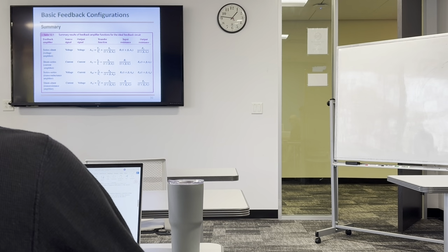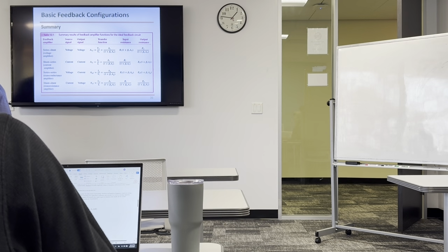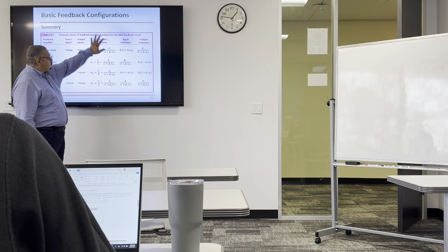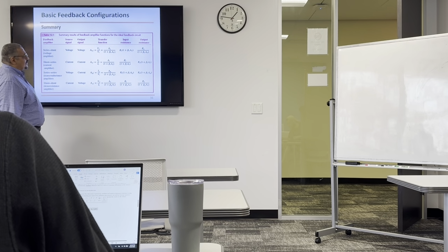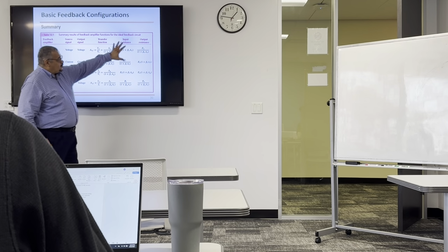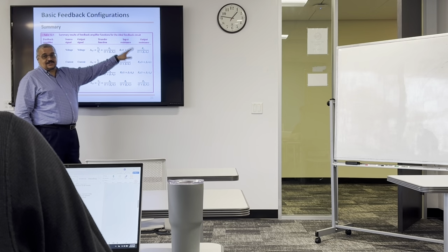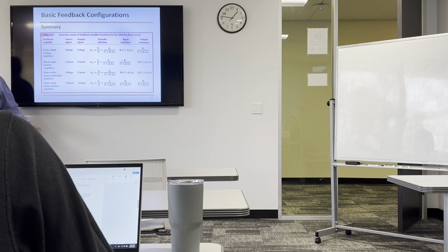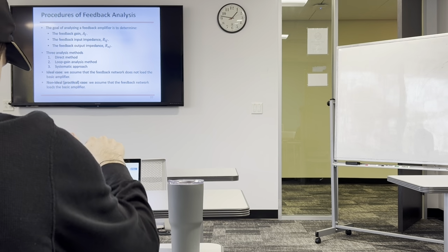So this is the main idea. With the feedback, you reduce the gain, which is the main disadvantage. But on the other side, you improve other parameters like the input impedance and the output impedance, depending on the topology or the configuration. Okay.